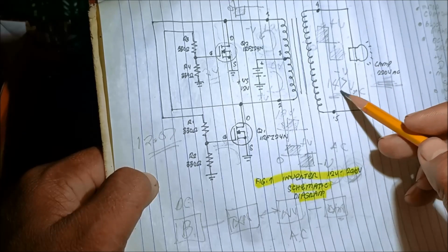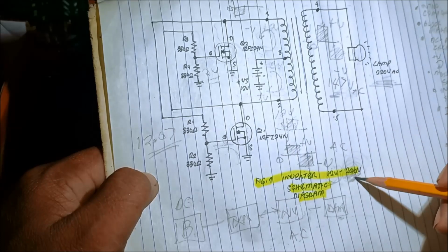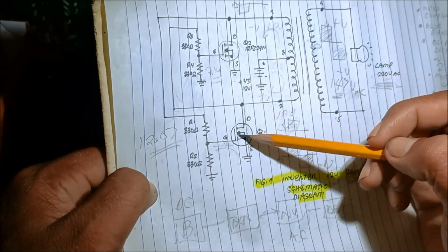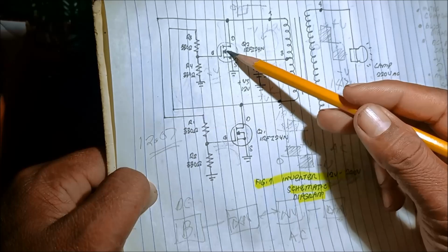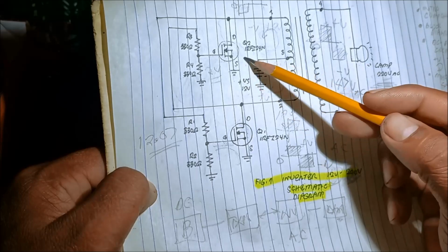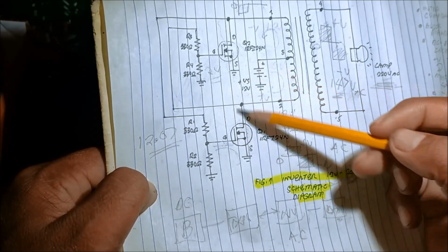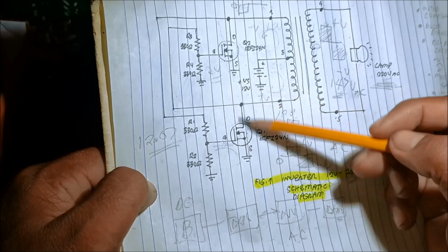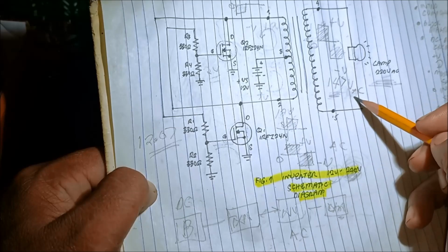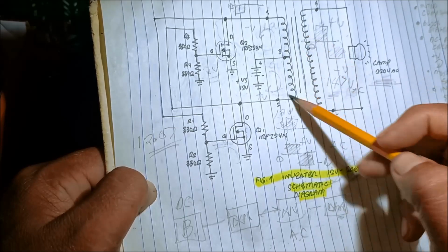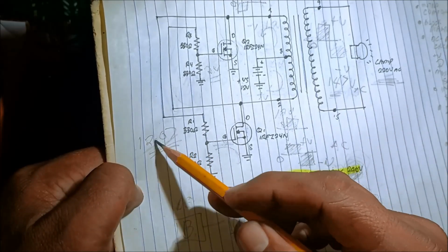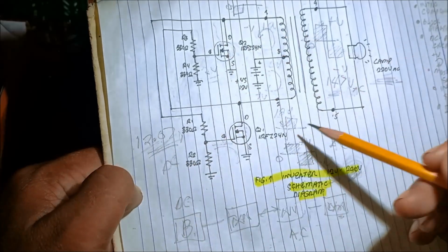Why are we not capable of producing 220 volts? Because we have no separate oscillator. We have just an oscillator, at the same time a driver of the transformer. We cannot control the oscillation of the MOSFET. We have no separate oscillator. That's why in this case we just have 147 volts AC, and due to the transformer loss, there's also a voltage drop, 12.07 volts DC into the battery.